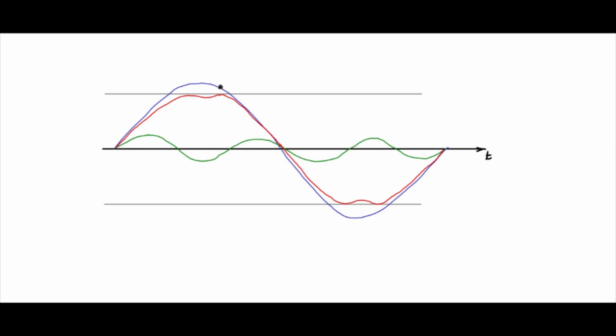So in space vector modulation, we use this technique of trying to get more fundamental out of it. A normal sinusoidal will give you just about 100%, whereas space vector PWM, because of this, can give up to 114%. So that is the extra mileage that you can get. So that is why a third harmonic is added.